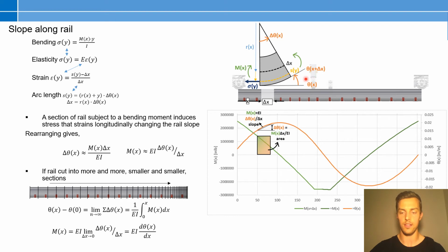And kind of in the same process as we were doing before, we can start at the initial slope and go from section to section and add up and resolve the approximate solution for the slope. And just as a gut check here, it makes intuitive sense that the slope will start positive and gradually incline until you reach where the forces are, and then become negative, as indicated by a gradual decline.